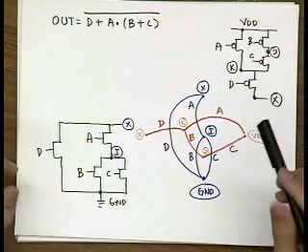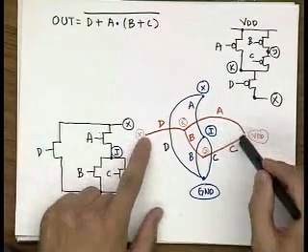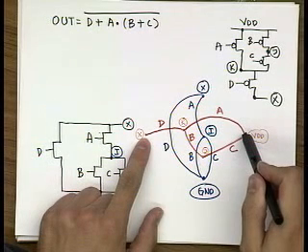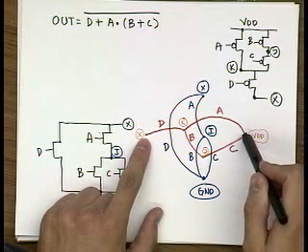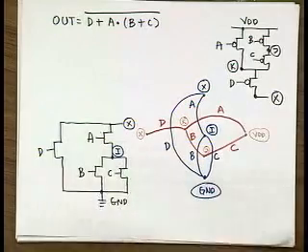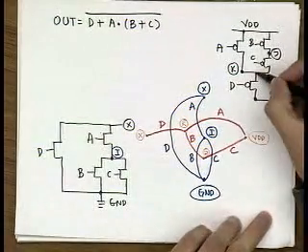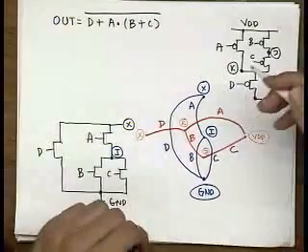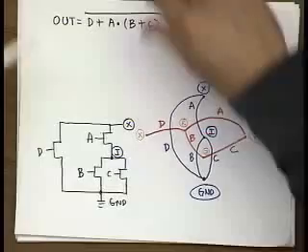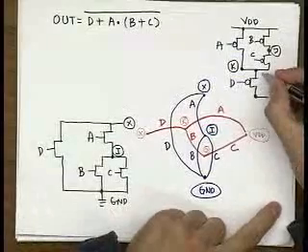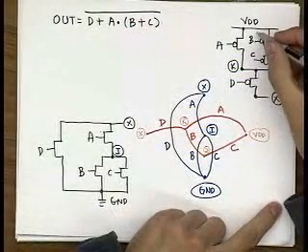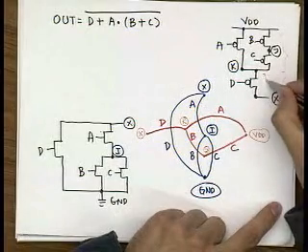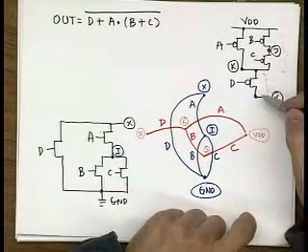So now here's a question. What if I, for example, flipped X and VDD over here? I can do so, right? It doesn't change anything. So what this would actually mean is basically that these two sub-networks would be rearranged. You would just have D on top connecting to VDD, and then you would have this entire subnet on the bottom connecting to X.